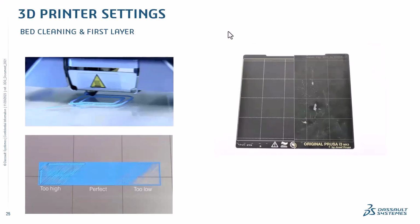And also, in order for your first layer to be stuck to the bed, your bed has to be clean, and therefore it is always advised that after each part that is printed, you clean your bed. You make sure that the bed is cleaned properly. You can use IPA or isopropyl alcohol to clean your bed, but please be aware and use this under the guidance of your school teachers who are mentoring you, because if you use the wrong chemicals, it may cause damage to your printer.